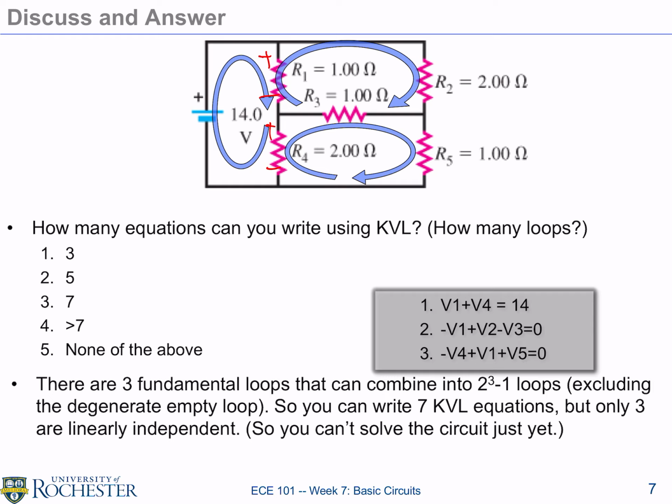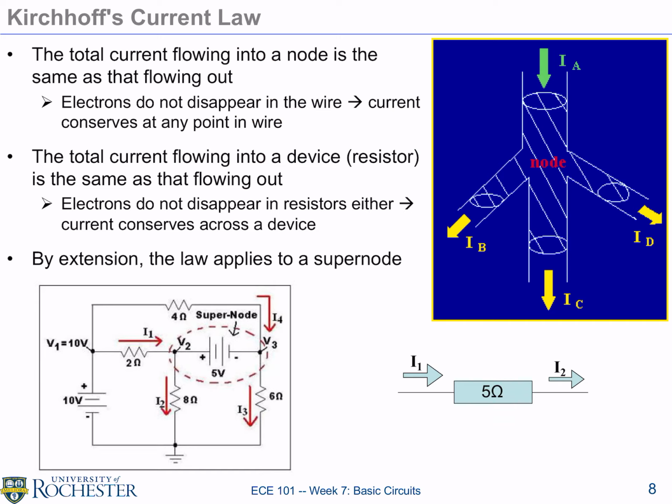So that's not enough. What else do we know? Well, that's KCL, Kirchhoff's current law. And that's really, again, just conservation. If you have a node, being multiple circuit elements coming together. They're usually drawn in plots as a bunch of wires connecting together, right? But really wires are just for visual purposes.